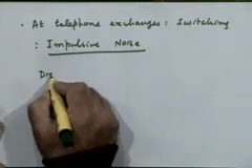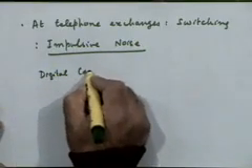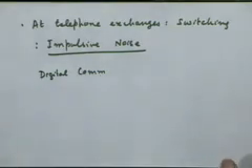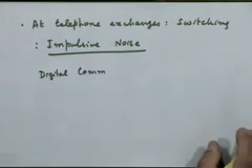So impulsive noise is something that we must particularly worry about in digital communication, right? Not that it is not important for analog communication, but it is very crucial to worry about in digital communication, because data would be entirely lost in the interval in which this large amplitude pulse interference takes place. It's obvious. I don't think I have to explain that too much. All right. Any questions?